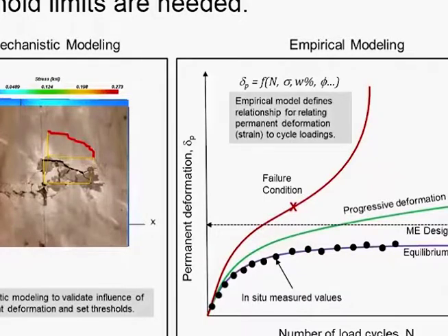And this was an aha moment for us because we were on a project and we were measuring modulus, and we measured modulus here and we measured modulus here, and it was pretty similar. But the permanent deformation over there was much more than it was here. So from a design standpoint, we're treating it all the same. Probably shouldn't be though.